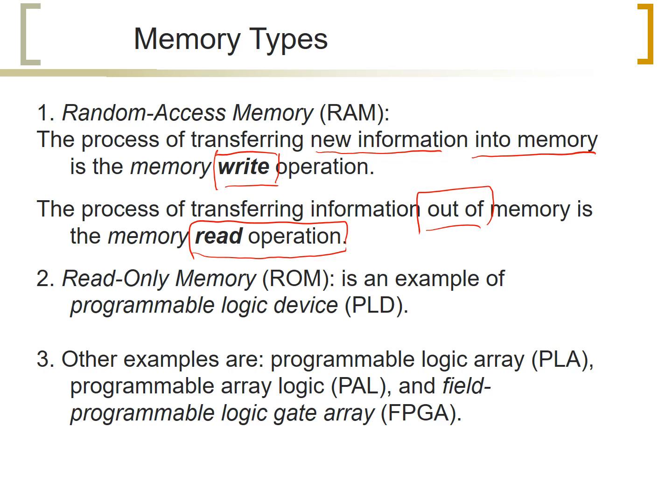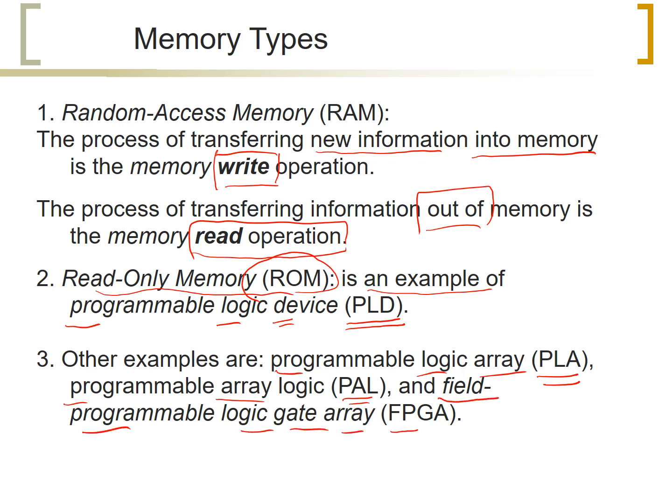So we write into the memory and we read from the memory. However, on the other hand, the read-only memory, where we can only read from this memory, is an example of what we call programmable logic devices. We abbreviate it as PLDs. There are other examples of programmable devices, and these are respectively the programmable logic array, called PLA, and the programmable array logic, called PAL, and finally the field programmable gate array, which is called FPGA.